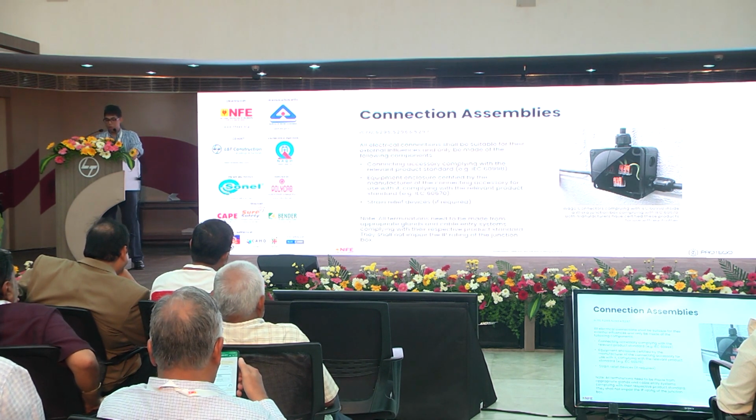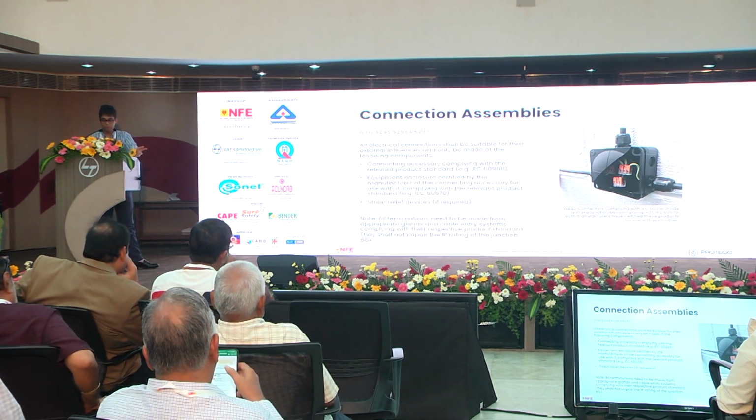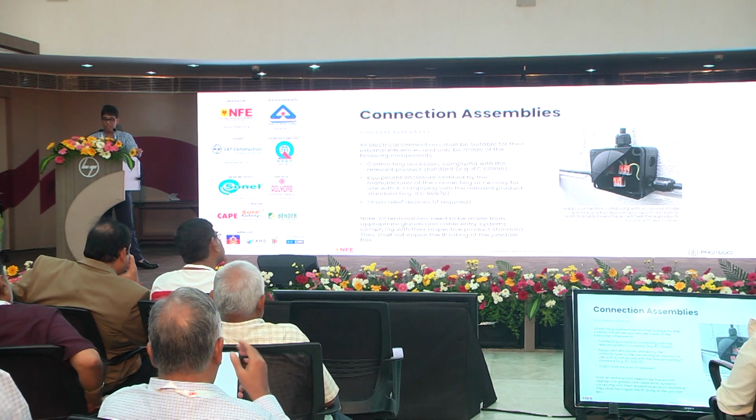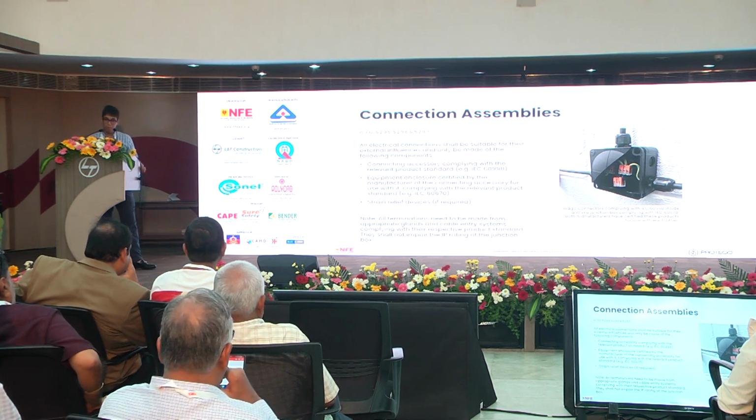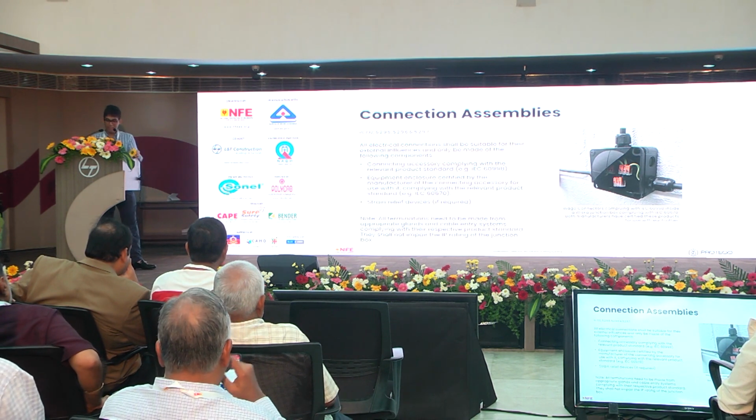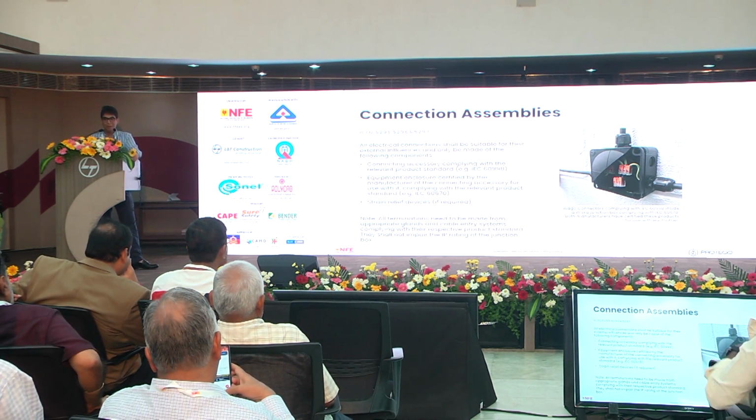In the case of Wago terminals, if you want to achieve a maintenance-free status, then you need to use it with a junction box that it is certified by. So two brands, Wago and Wiska, have actually certified their junction box and connectors for use with each other. I was going to get a sample to show you, but getting that sample through airport security would have been a bit of a problem.